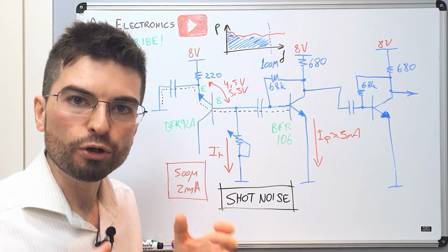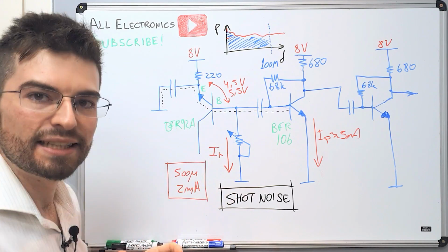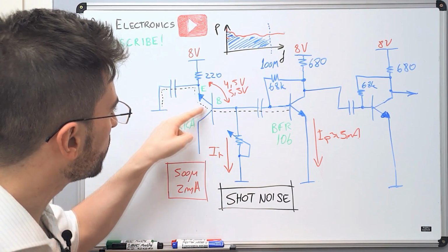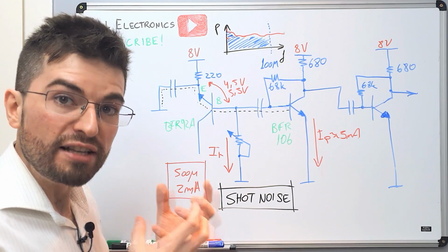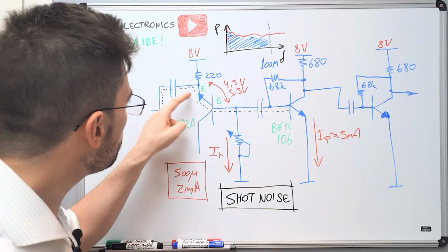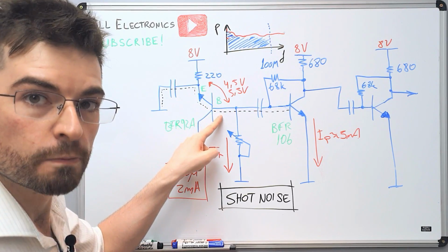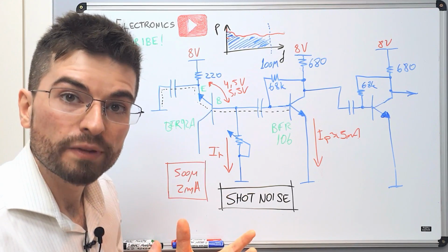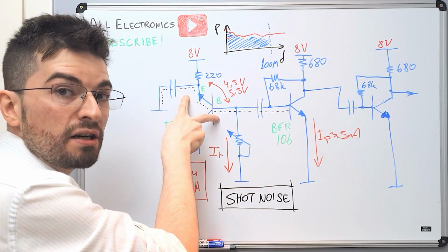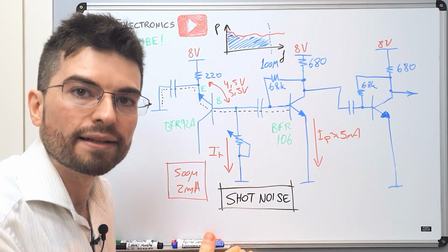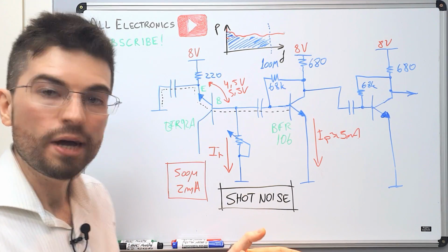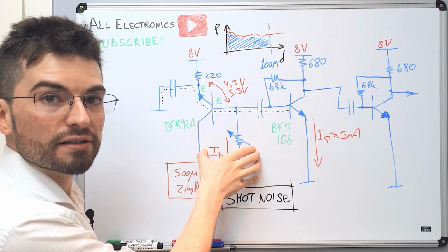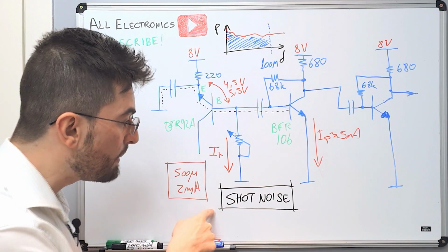The only thing that we know when looking at this as an electrical circuit is that on average we have this amount of current, reverse current, that is physically an amount of electrons jumping the PN junction potential in an average term. But in practice, this flow of electrons is random, and this modulates the voltage here randomly, generating white noise. The only thing that we can control is the average aspect that is represented here by the reverse current. That's actually fascinating. Go read about shot noise.